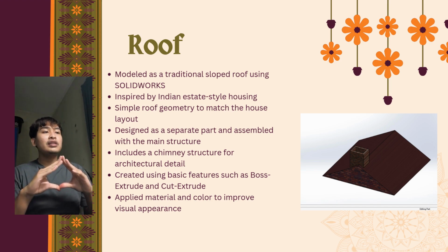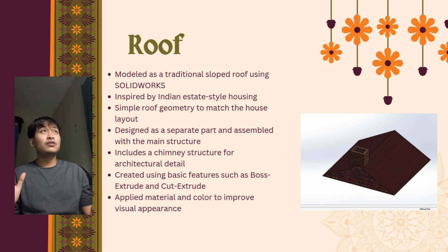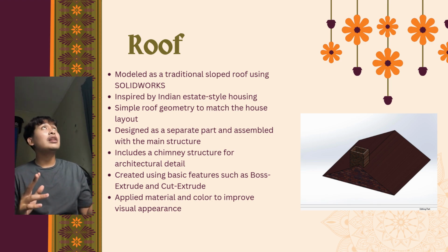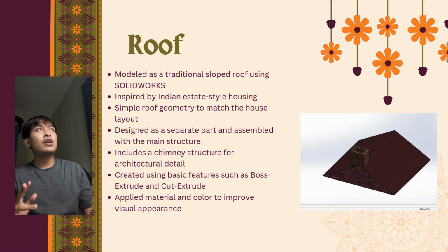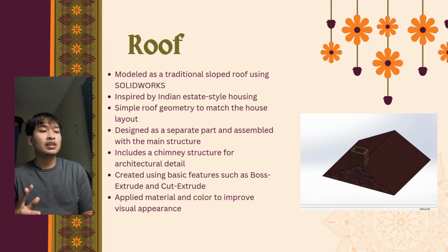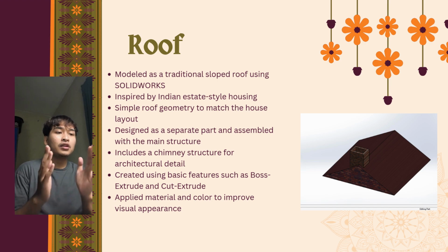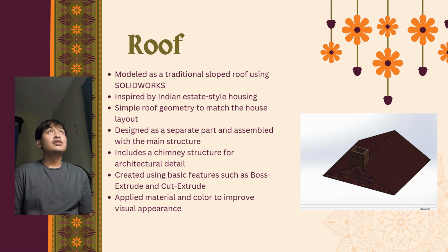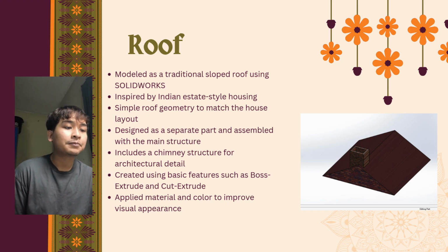Just do the triangle and then extrude boss base, in which I calculated the length of the extrude to be 14500 mm if I'm not mistaken, and the length of the roof, the triangle base, is about 13500 millimeter.